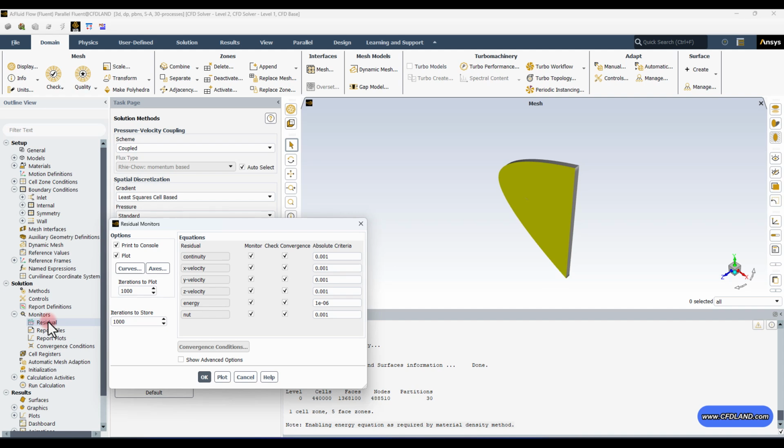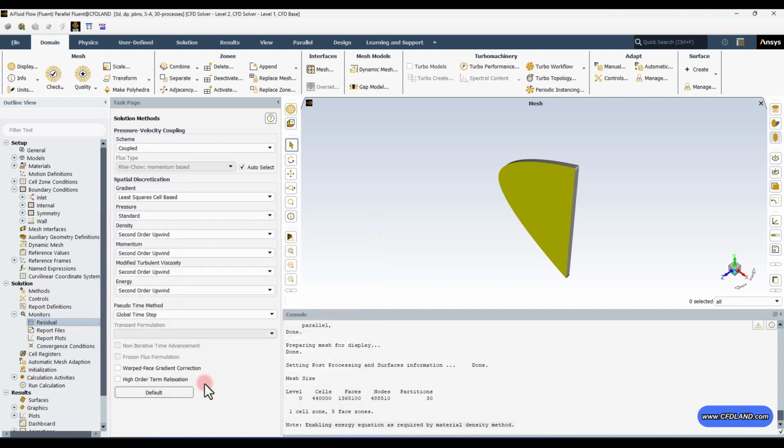So this time, I'm not going to trust them. I'm going to monitor the drag and lift coefficient during each iteration and check it by myself. So the simulation wouldn't be stopped by residuals. In order to deactivate these residuals, you can uncheck these boxes. So as the substitution, I'm going to define new reports for drag and lift coefficients and monitor them during the